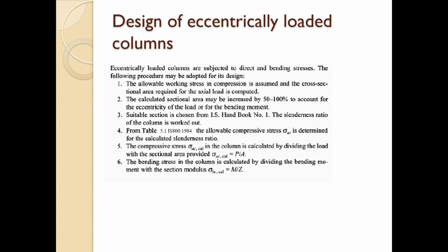The slenderness ratio of the column should be worked out. From table number 5.1, we have to check the allowable compressive stress for the calculated slenderness ratio.